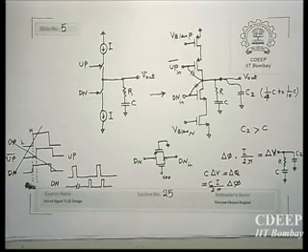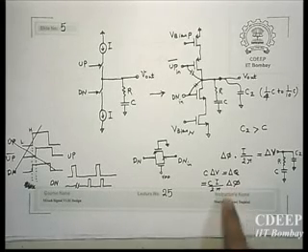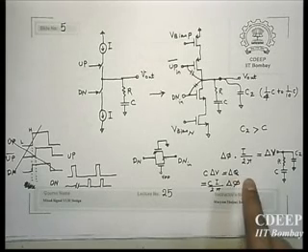So the amount of delta Q which remains and doesn't discharge because of this mismatch will get translated to a phase error of delta phi. And the value of this delta phi is determined by this relation. In fact, delta phi will be 2 pi delta Q upon Ci.